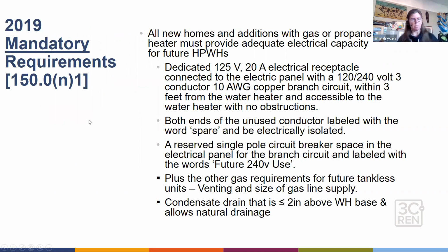So, mandatory requirements. I mentioned the pre-wire. All new homes that install a water heater that is either gas or propane must provide capacity for future installation of a heat pump water heater. So the code is saying we want to make future retrofits easier and reduce that capital cost later on. So you have to have a dedicated